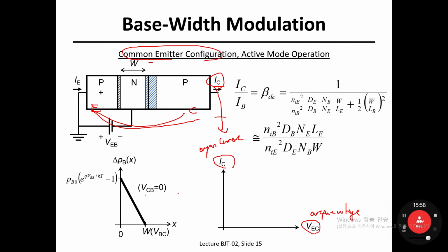So this voltage difference, because the emitter is common and your output node is the collector. So with respect to the common node, which is the emitter, how much voltage you get at the output node. So this VEC, with its plus and minus, indicates your output voltage, okay?